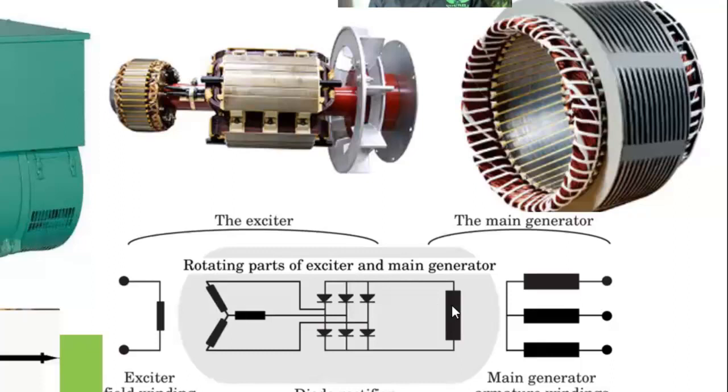So this is the feed winding, and the two leads that come out of the feed winding go straight to the diode plate. This is the diode plate, okay? So one end is to the negative terminal of the diode plate. I will show you guys the diode plate later. This is to the negative terminal of the diode plate, while the other end is to the positive terminal of the diode.